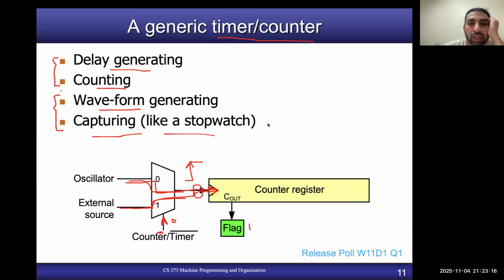By internal clock here, we basically mean the same clock which is used by your AVR microcontroller. So timers are also using the same clock. These statements will become more meaningful for you when we cover the remaining slides, but at this point maybe they are not crystal clear. So just keep in mind that timers operate on the clock signal, and when we want to use a register as a counter, then it is controlled by an external event signal or an external sensor.